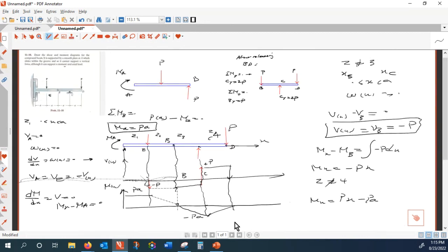All right, so this is an example of a composite beam. You have hinged two beams together. The right-hand side is like a seesaw. You have a support in the middle. Two forces are acting vertically down. The support will take double the force upward. And on the left-hand side, you have something like a cantilever, but a cantilever which cannot take a vertical resistance.